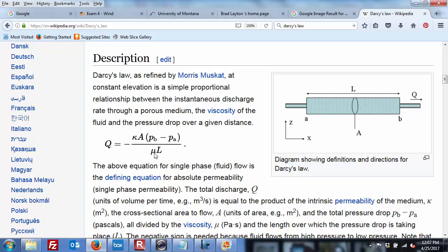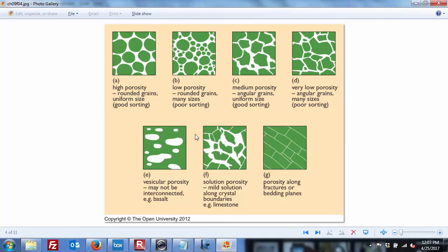This is the viscosity, so this is how sticky the water is. And for the hydraulic systems that we're talking about in geothermal, that's not going to change. What does change, this is the critical number right here, is that kappa. And that's just the permeability or the porosity. So if we go back here to our figures, this is going to have a relatively high kappa. These are all relatively high. You start looking here and it's relatively low.